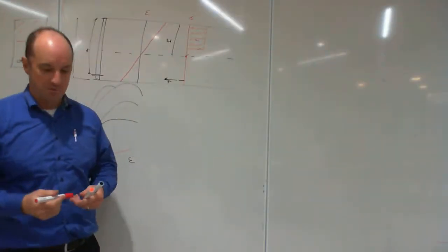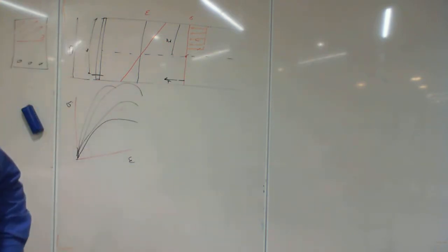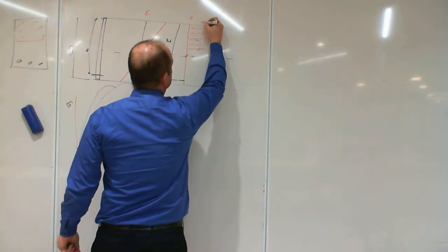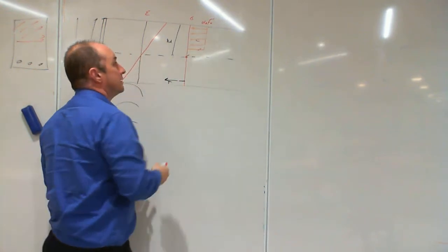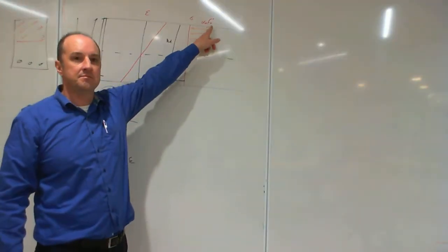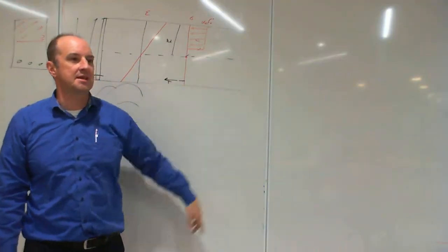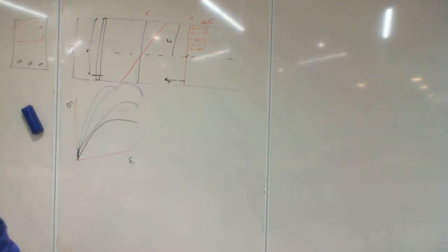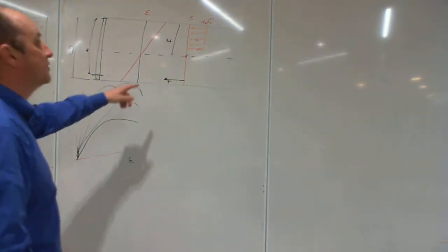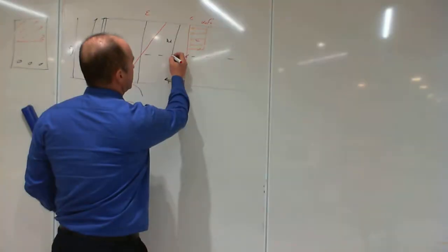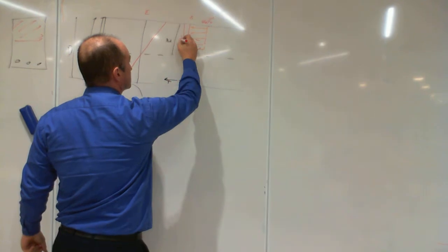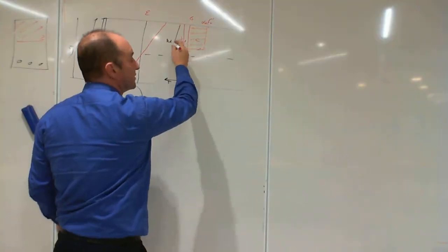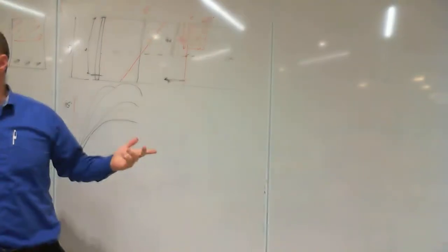And the dimensions of that are alpha 2 times f'c. f'c is the strength of our concrete, so 32 MPa. Alpha 2 is a number less than 1, so it's a proportion of our strength of concrete. And the height is not all the way down to the neutral axis. It is gamma times Ku times D. So gamma is another number which is less than 1.